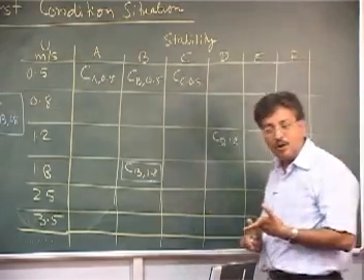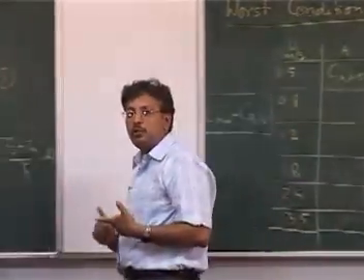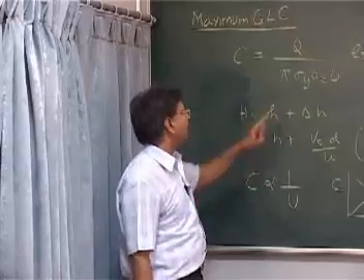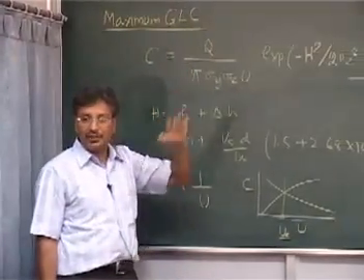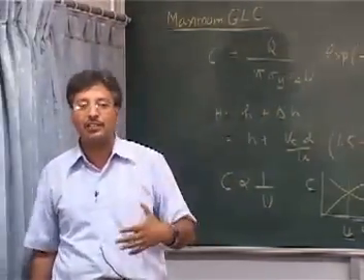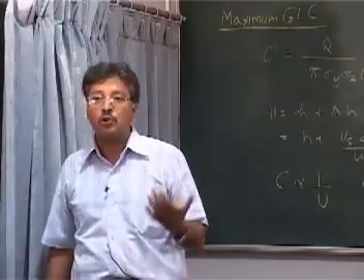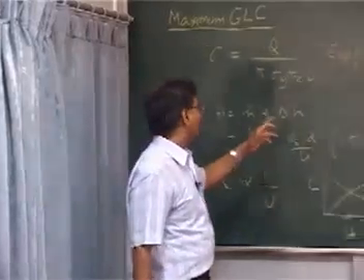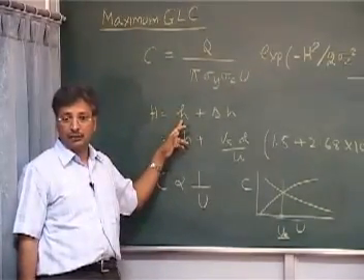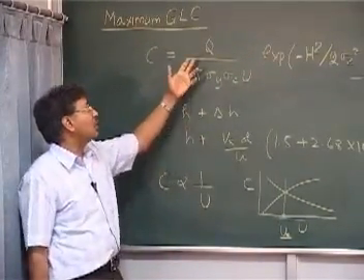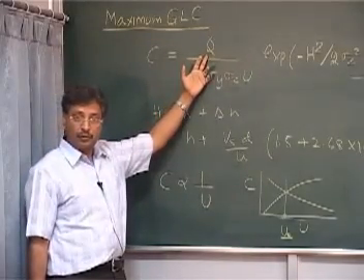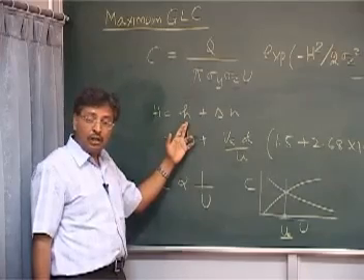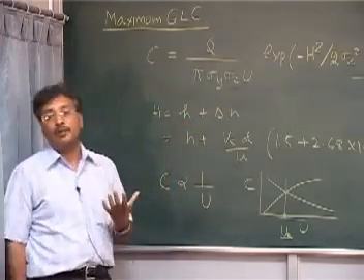And the designing part, how you can design the things, you have only two things in your control. The control you have is on this Q. You can ask them to control the pollution, you can ask them to use a better coal, you can ask them to go for a better technology. Or you can say increase the stack height. Both the things you can do. As an engineer, you will say, well, decrease your Q or increase your H or other variables, because you have to optimize the variables.